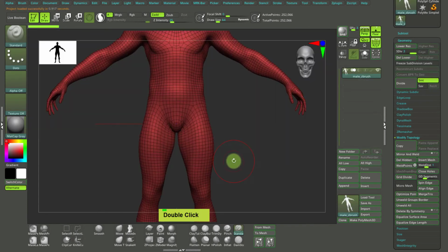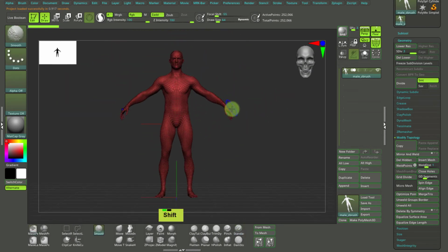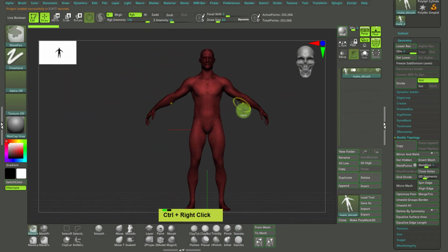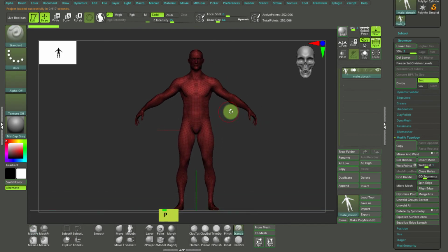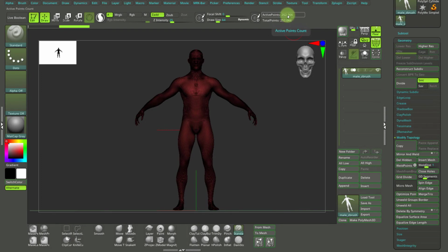No, we don't want to save this particular project. Yes, this is a project that's coming with ZBrush, and perspectivity turned on, and it has subdivision levels. Let me delete the lower subdivision level. Even if we have deleted all of those, we have this high resolution, and this high resolution is even lower than the 500,000, so it is absolutely doable to have a full body with 500,000 polygons relatively in good quality. Okay, as a base mesh at least.